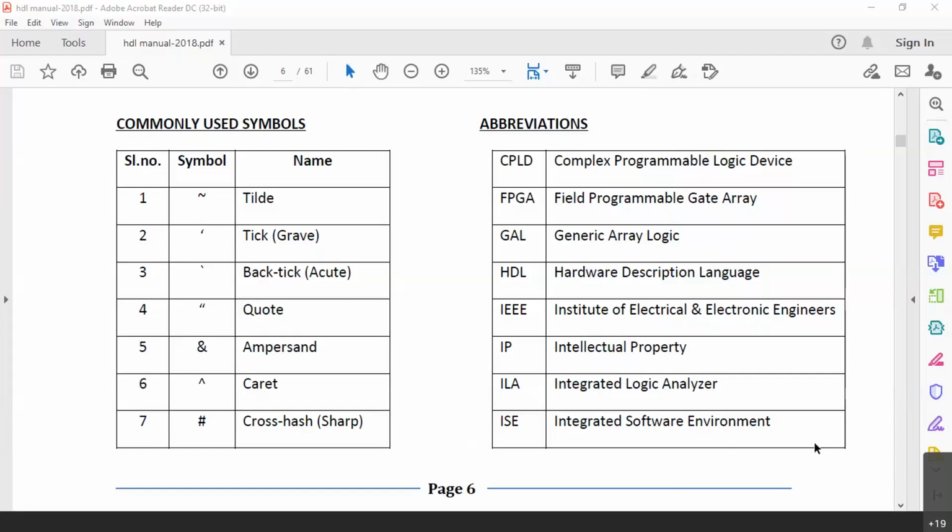Whenever you write a software program, in the beginning you require a compiler for checking syntax errors. In the case of C language, after the compilation you will have the linking, right? You will have a linker, and that linker will gradually help you in executing the program. Here in the case of HDL, we have a compiler for checking syntax errors. Later on, we do not have any linker because we are getting the FPGA programmed. So we have something called a simulator.